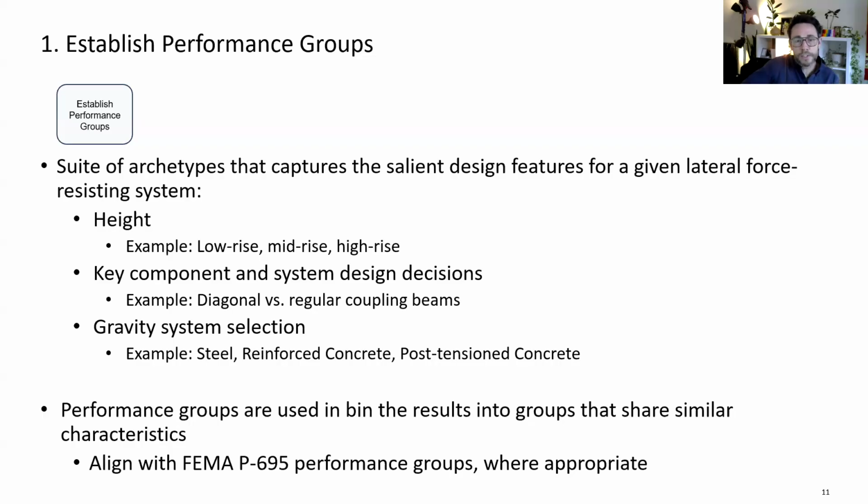Once we have the suite of archetypes, we create performance groups by binning archetypes that have similar characteristics. In our work, all of the systems that we considered have a precedent in the sense that there's a FEMA P695 study. So we've tried to align our choice of archetypes and performance groups with those available in the corresponding FEMA P695 reports.